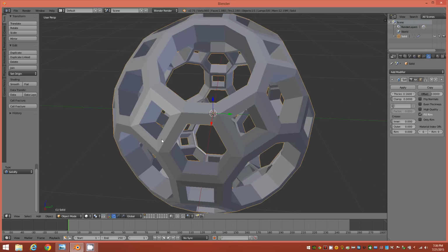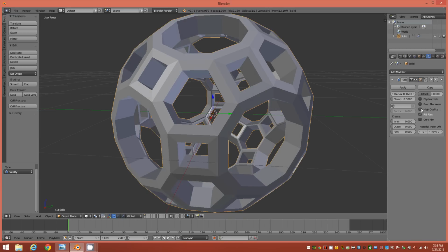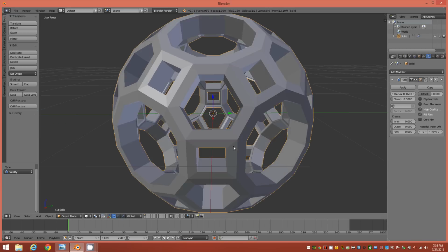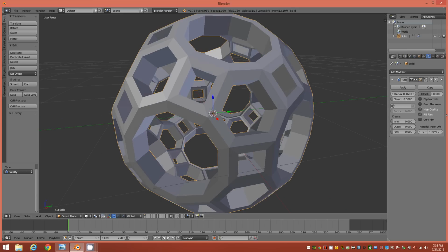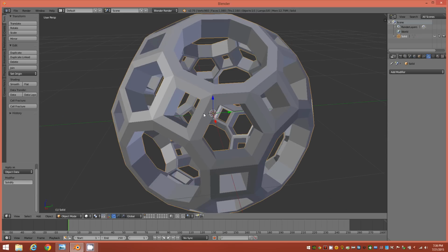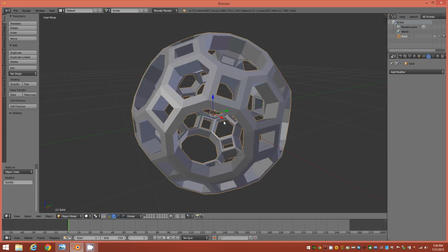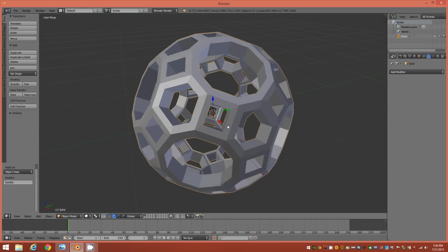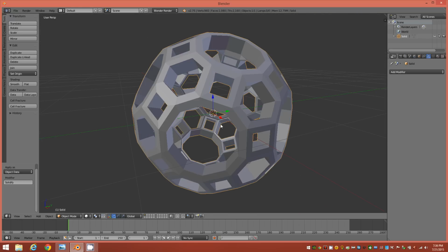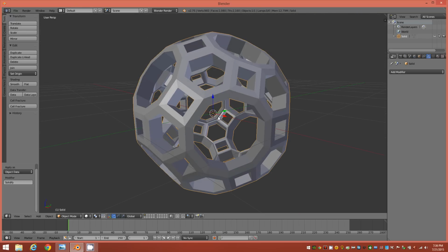Okay. And I'm going to just check the high quality. Alright, in the options there. Alright, and I'm just going to apply the solidify modifier. Okay. Now the next step, make sure that everything is centered here. Your orientation gizmo is right in the center still.